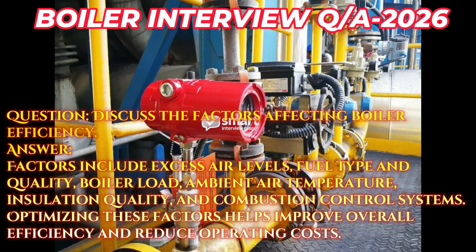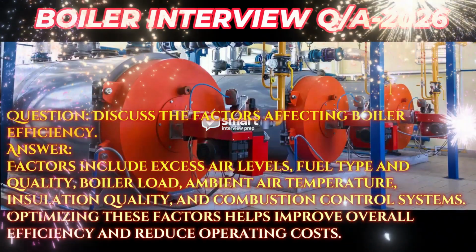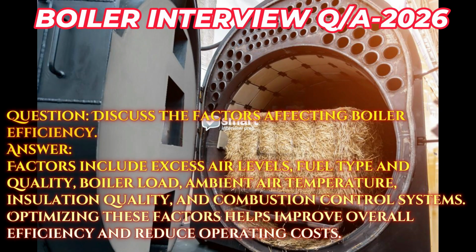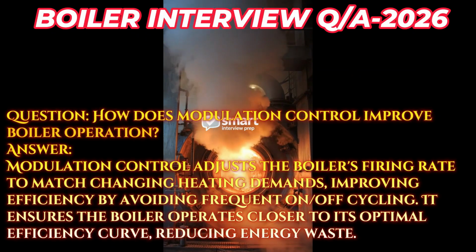Answer. Factors include excess air levels, fuel type and quality, boiler load, ambient air temperature, insulation quality, and combustion control systems. Optimizing these factors helps improve overall efficiency and reduce operating costs. Question. How does modulation control improve boiler operation?